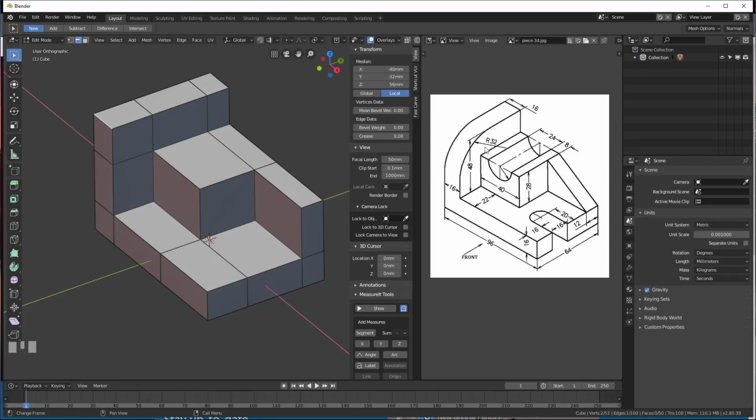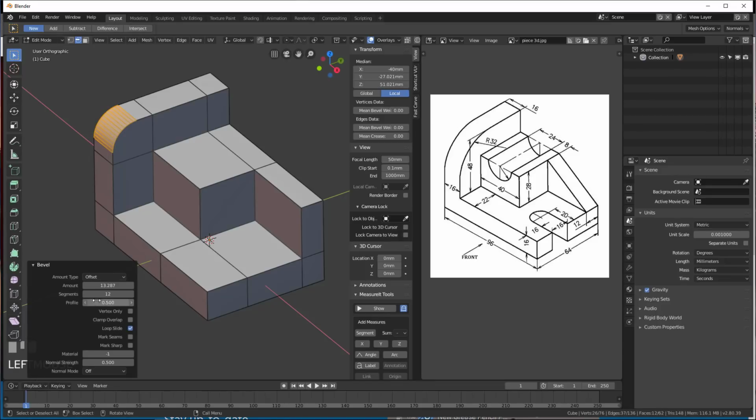We can notice that here the radius size is 32, so I can manage my radius into my beveling. So if I just do Control B, increase this with the scroll mouse here, and I will go into my bevel options there. So I have an amount of 13. If I increase this, okay, you can see that it increased, but more than 20 it's not possible, because here I have this line that doesn't allow me to go through, okay?